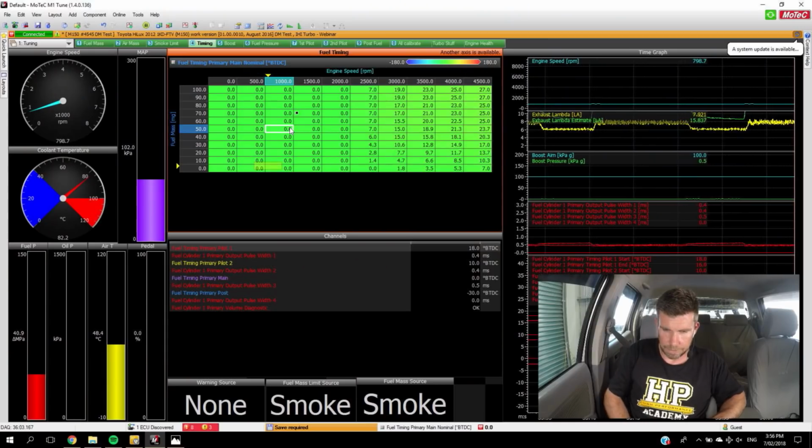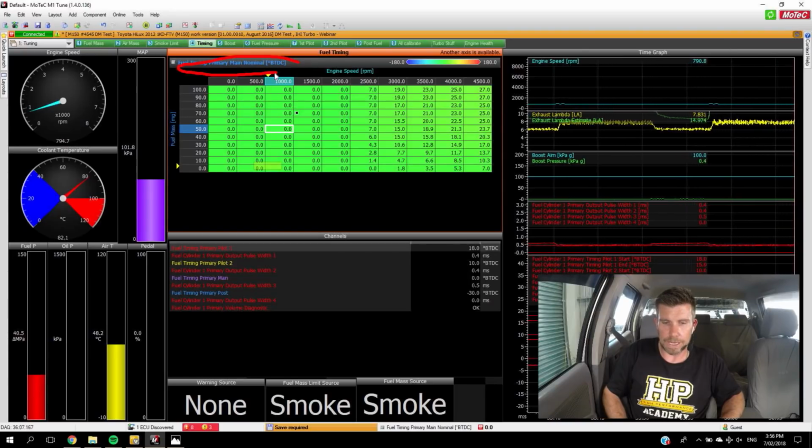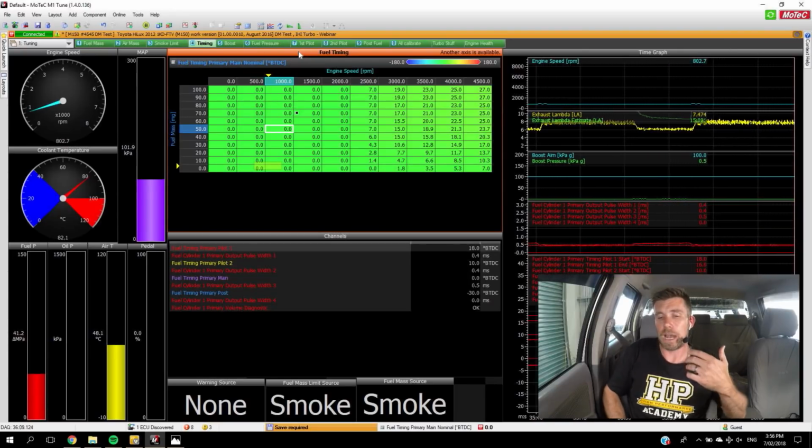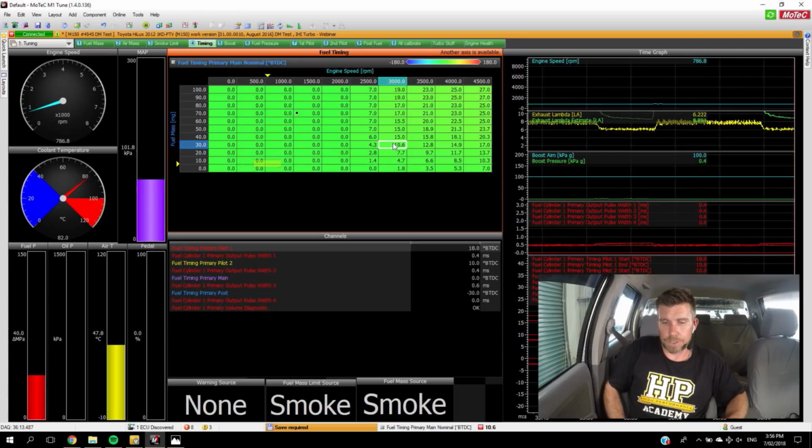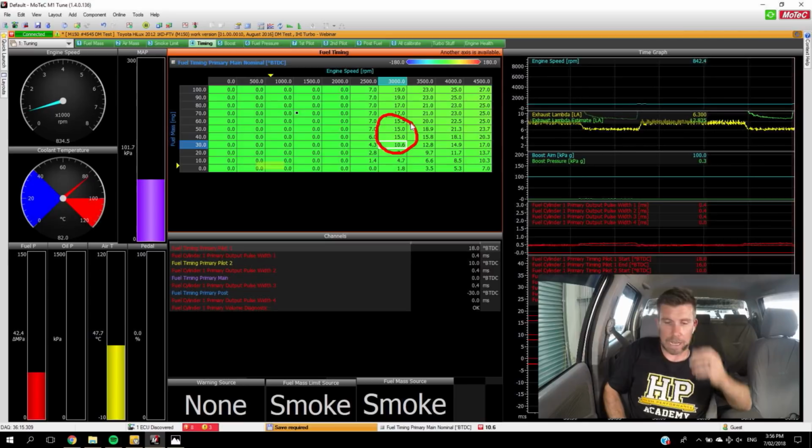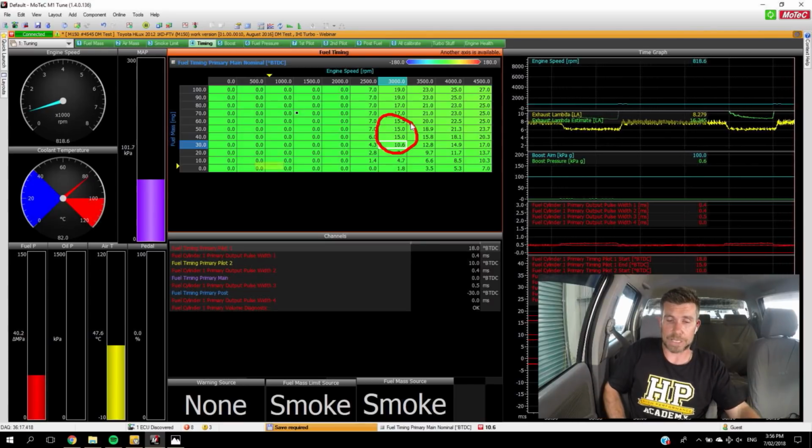This time we're going to see how our injection timing affects our torque. So if we just jump into my laptop screen for a moment, we'll get ourselves up and running here again. This is our fuel timing primary table, where we're defining the timing for our main injection pulse. And what we're going to do is come up here to around about 3000 RPM, and again we'll have a look at the effect of our timing value.